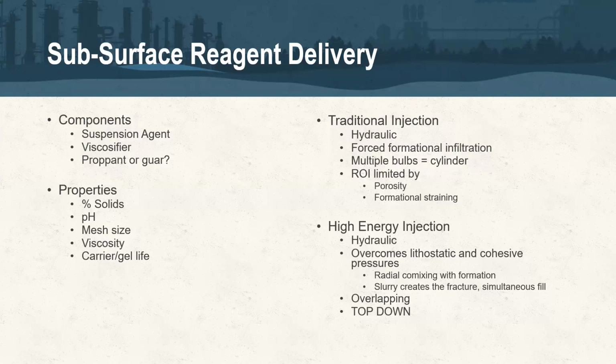Again, because there is some variability in using a synthesized iron sulfide here, there is a little bit of heterogeneity in the type of particle sizing and solids we're dealing with. But typically, most of these formulations end up being somewhere between 8 and 11 pounds per gallon. So it's a very true slurry that has to be injected. So it does take very specific injection equipment.